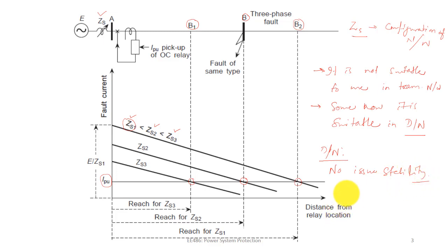Nowadays it is becoming active, but it is not interconnected, it is a radial feeder, and sometimes if the relay maloperates, even then only a brief interruption happens, and then it is fixed and the supply is restored. So therefore it is not an issue in the distribution network.